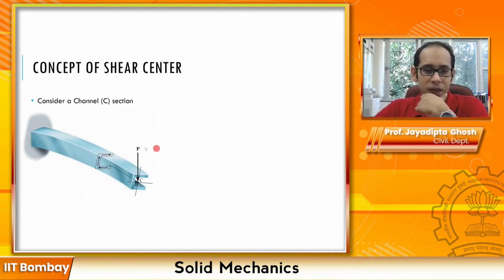Now this is again a similar kind of beam which I have taken, where the load is applied through the centroid. Now if you take an internal section over here, this is the resisting force that you are having. This resisting force equals P, and then because of the shear flow, remember we have considered the shear flow over here, you are going to have these horizontal loads which are acting on the top flange and the bottom flange over here.